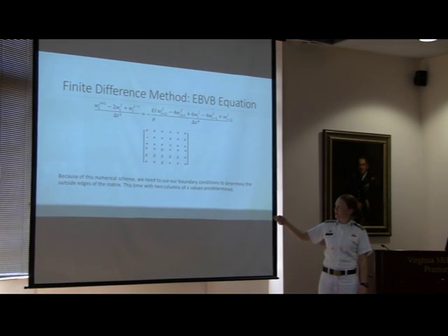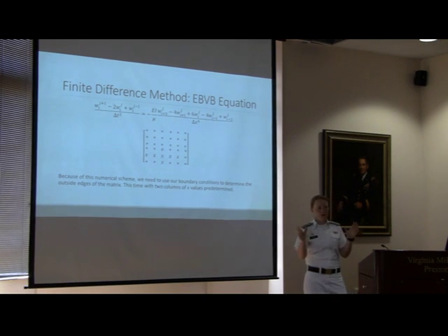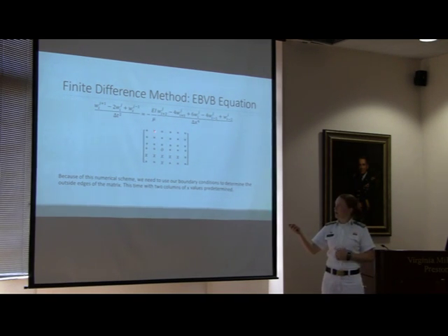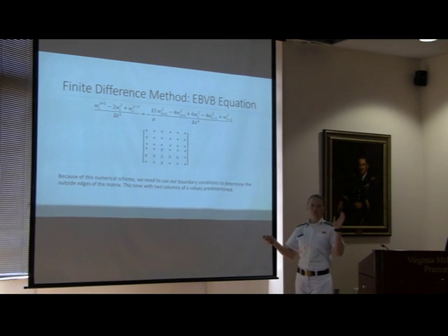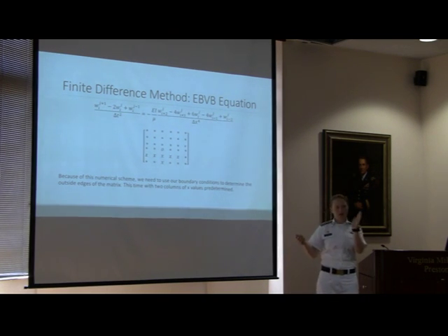Over here is where we look into our sets of 4 boundary conditions. So here our initial position is going to be 0 because it's secured on this end. And then using that, we can calculate out another time step with a forward difference approximation here to determine what it would be one movement in from that secured position.